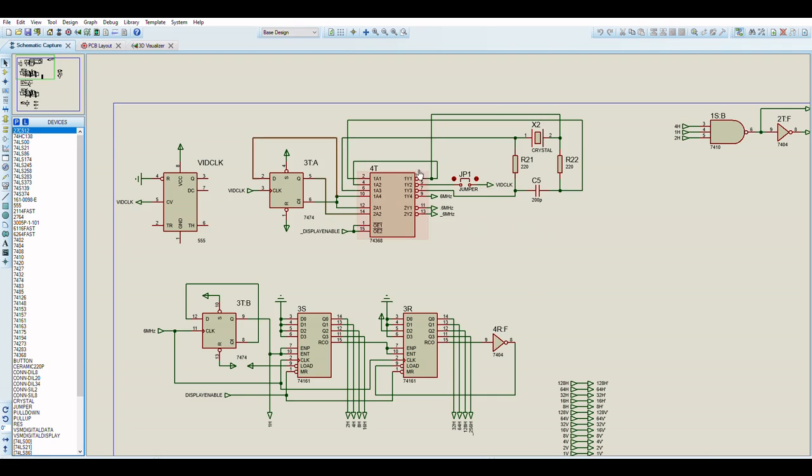It loops around and comes in through this flip-flop here, and then it will circle around like this. So it's a very stable setup, and this hex inverter generates a couple of 6 megahertz clocks and an inverted 6 megahertz clock as well.